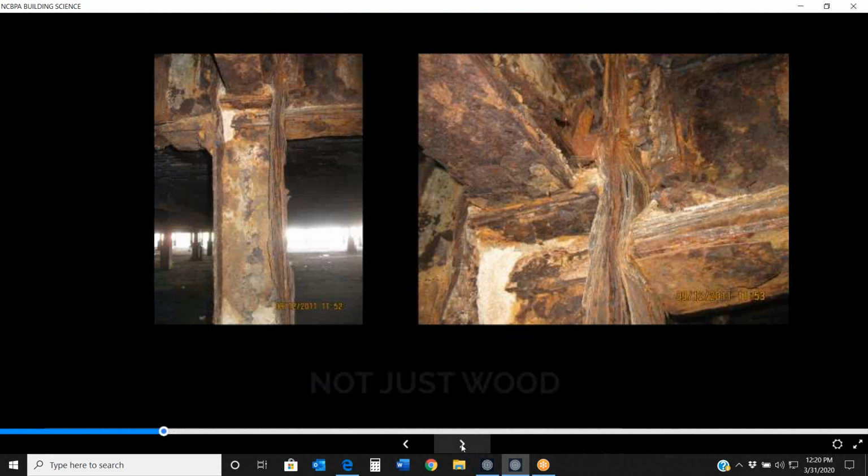It's not just concrete, it's not just metal. We know having a tight envelope and having a well-designed envelope is important for wood structures as well. We're going to talk about wood quite a bit in this presentation. Here's an example of some organic growth due to some moisture issues with wood frame buildings. Also, not only wood, this is metal underneath a parking deck inside of a structure, and you can see the effects that moisture had on this steel frame.